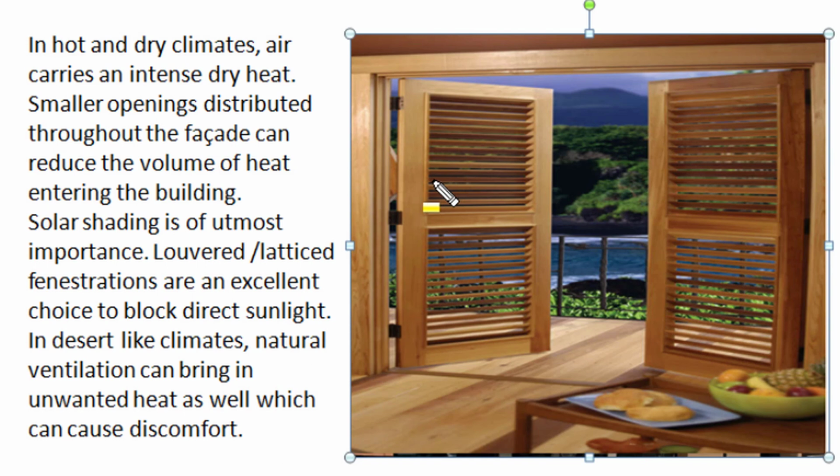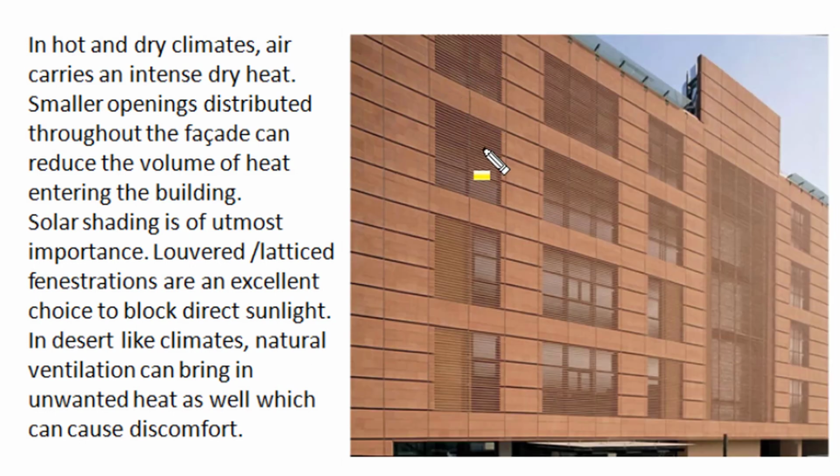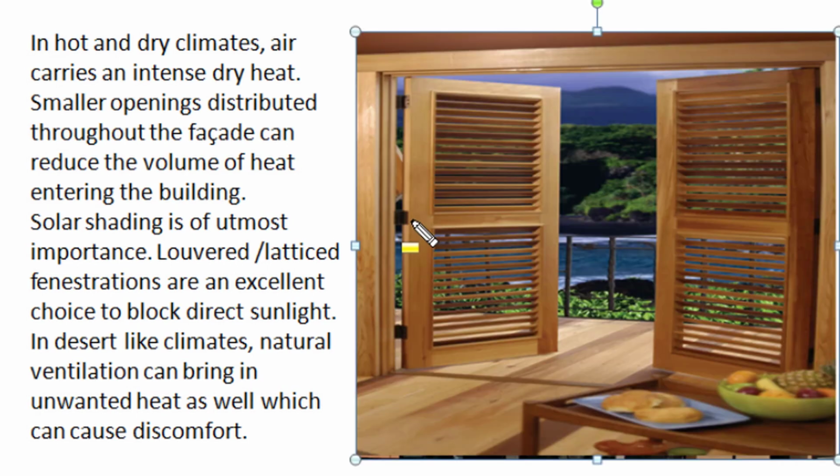In desert-like climates, if fenestration provide natural ventilation, then that ventilation can also bring with it some unwanted heat and which can cause severe discomfort to residents. So, appropriate control of shading on fenestration is also required in desert-like conditions. So, we have to adjust fenestration opening in those conditions.